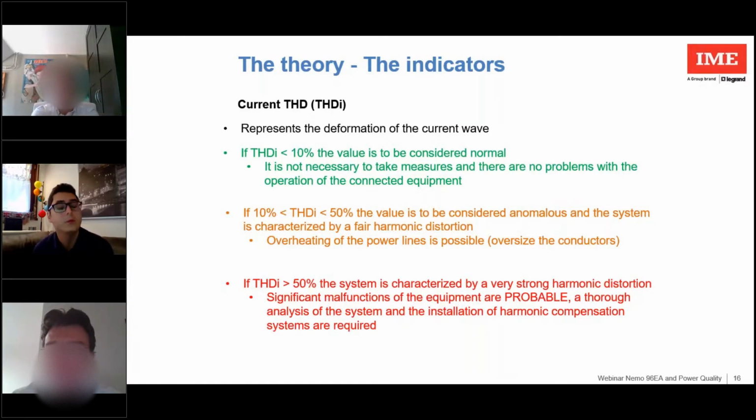But if you use a multi-session interface that converts from RS-485 to Ethernet, like the EF4E011, it manages the traffic on the line. You can have multiple questions coming from the PLC or the SCADA software and so on, and this interface manages the traffic, and you have 2 different answers for the 2 or more questions.